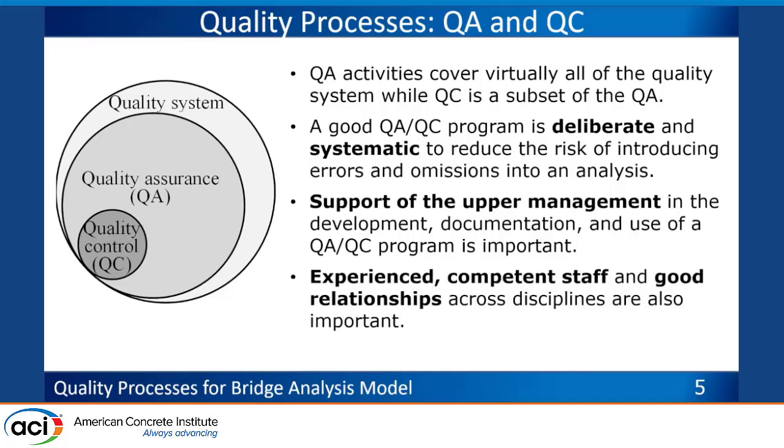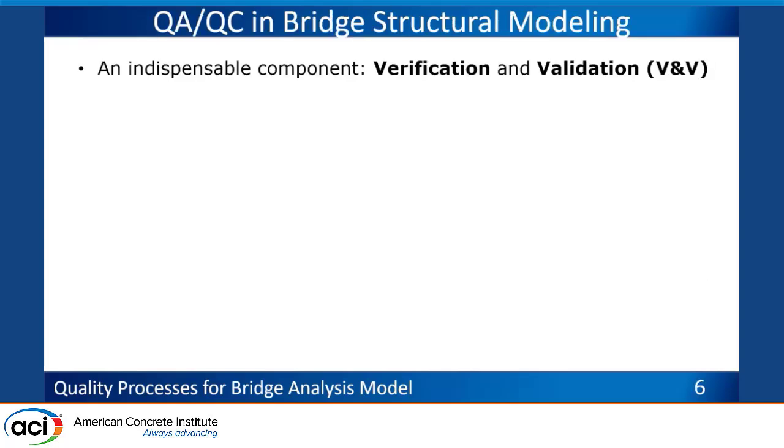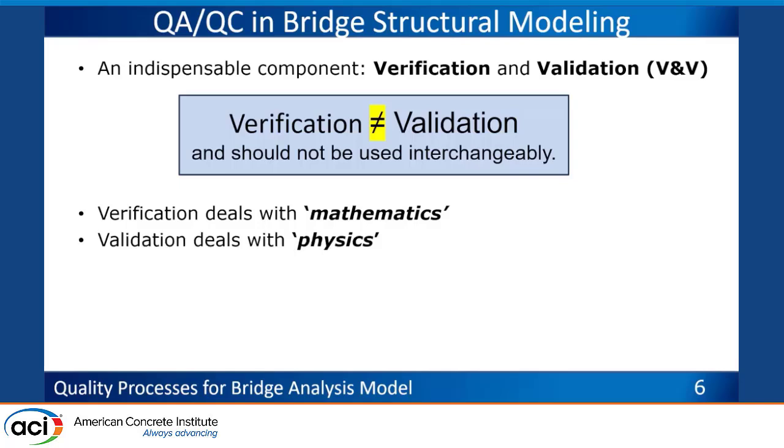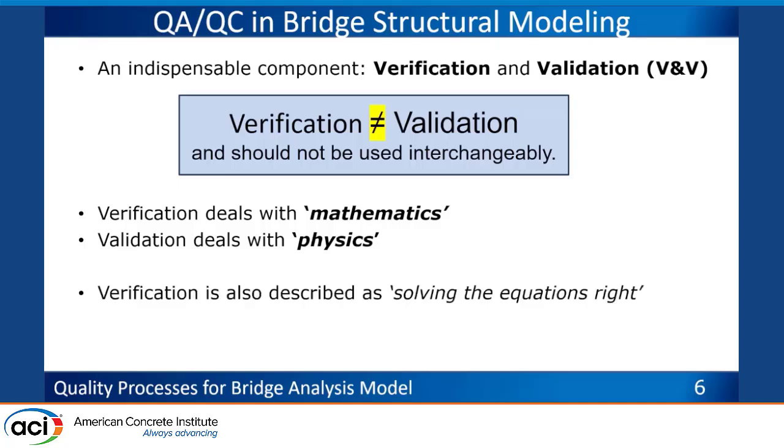So verification and validation are very important for bridge or any structural analysis models in terms of quality processes. These are used interchangeably, but they are different words. Verification is not the same as validation. Verification deals with mathematics, but validation deals with physics. So these are two separate concepts. Verification is also described as solving the equation right, but validation is described as solving the right equation.